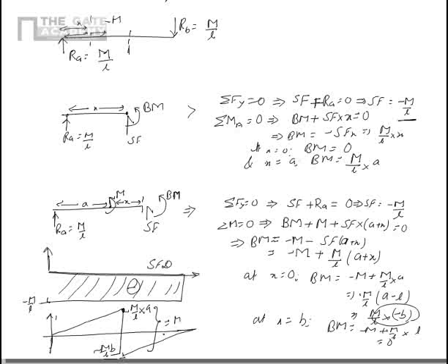So this is a very important case in my opinion, and it gives a lot of insight into how to draw the shear force diagrams and bending moment diagrams for cases where moment is applied. Moment application is something which is not very clear intuitively, because we don't know how to apply moment as a pure moment. Moment is always applied as a couple, which is like two forces acting in equal and opposite directions separated by a very small distance.